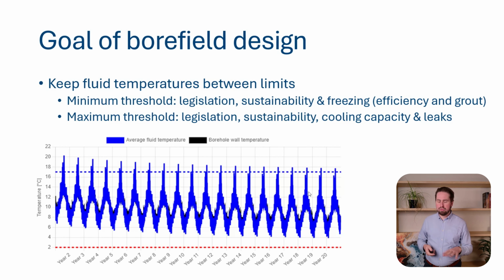Now, if you stay below 25 degrees, that is typically no problem, but if you go to 30, 40, 50 degrees, for example, if you're in a very warm country, then this expansion can become significant, and perhaps it's a good idea, at least for the horizontal connections or for the welds, to opt for a plastic material that is more capable of withstanding these warmer temperatures, because your typical geothermal probe, the plastic there expands quite a lot. So for the horizontal connections, please pay attention that there are not too many stresses on the welds itself in order to prevent leaking over time.